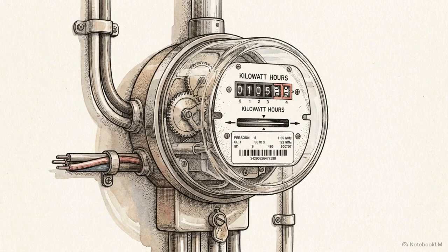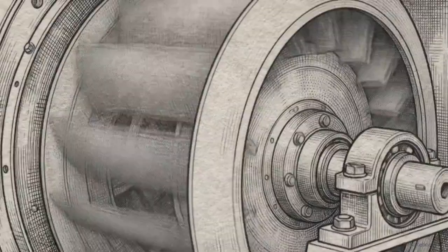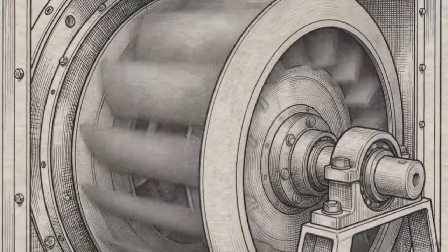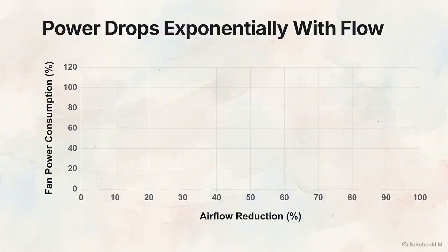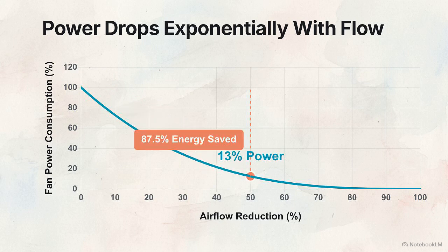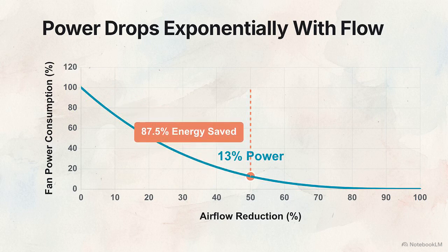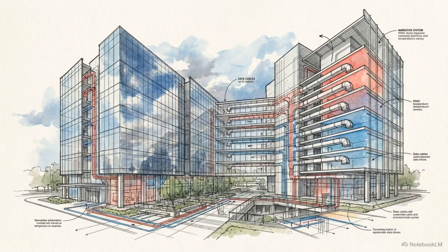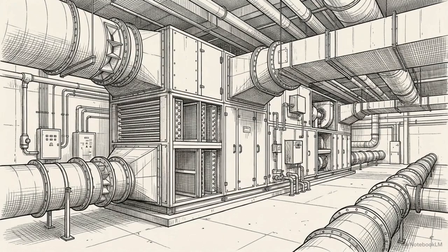The critical advantage of VAV lies in energy consumption. In most applications, the supply fans pushing the air consume more energy annually than the refrigeration systems cooling it. This graph illustrates the relationship between flow and power. It is highly nonlinear. As the required airflow volume drops, the electrical power needed to run the fans drops exponentially. By balancing the equation through delta Q instead of delta T, the VAV architecture trades absolute psychrometric precision for profound volumetric energy efficiency. These abstract thermodynamic manipulations require a rigorous physical architecture to execute.